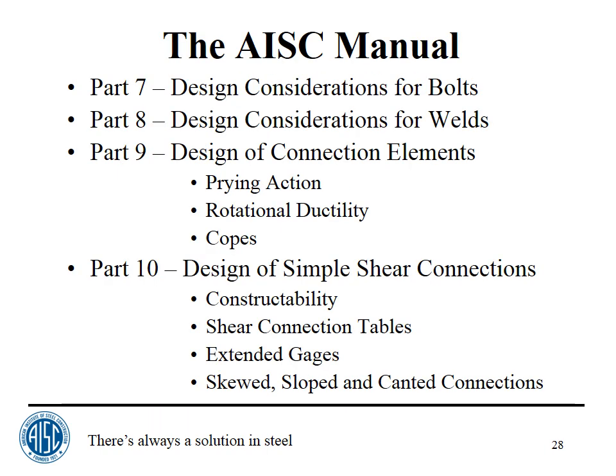Continuing with the manual, Part 7 is really all you need to know about design for bolts. Eccentrically loaded bolts, the theory that's used, there's a discussion in there of the inelastic and the elastic methods. Part 8 has to do with welds. Everything you need to know, I think, pretty much about the design of welds, strain compatibility and things of that sort.